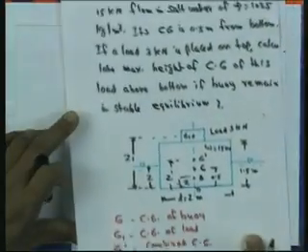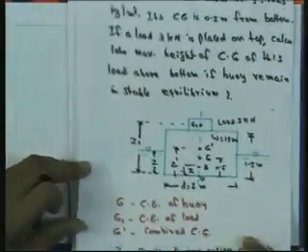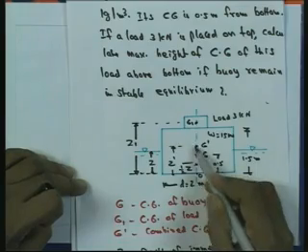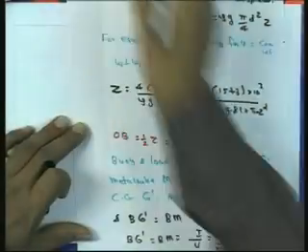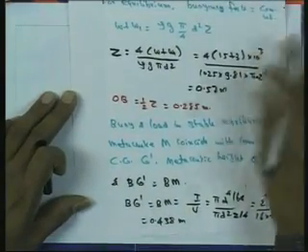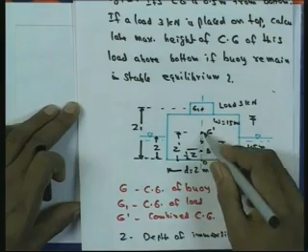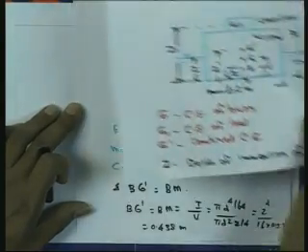Since it is in stable equilibrium, the metacenter M coincides with the combined CG G dash. So M and G dash coincide, so we can write G dash M is equal to 0. And now BG dash, the new position of the center of gravity, is equal to BM.